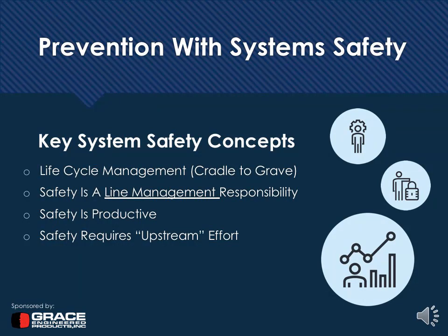human machine as well. So, for example, if we're talking about an electrical motor, the first time we energize the motor, when it's brand new, it has a higher than average failure rate when you first energize something. As the motor runs over its normal life cycle, it tends to work just fine with normal maintenance. But near the end of its system life cycle, we need to tighten up the maintenance processes and so on, because we recognize that the motor is near its design life. So the key point to understand about life cycle management is that the safety system needs to adapt to where they are in the life cycle.